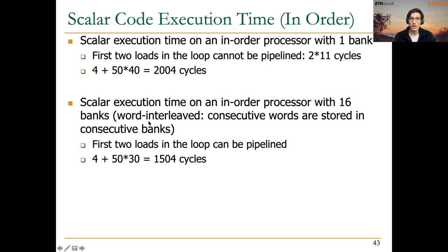How can we make this more efficient? How can we accelerate this? Well, instead of having a single bank, let's have more than one bank. We can also use banked memories, and we actually do it, banked memories for sequential processors as well, because this way we can hide the latency of the access to memory, right? And we can obtain much more throughput from memory.